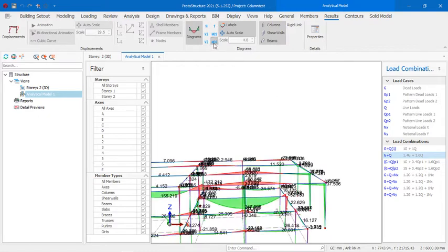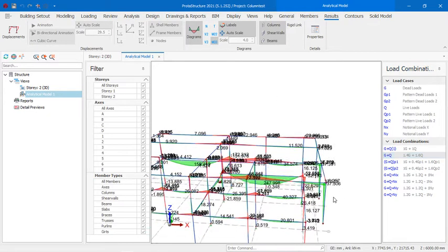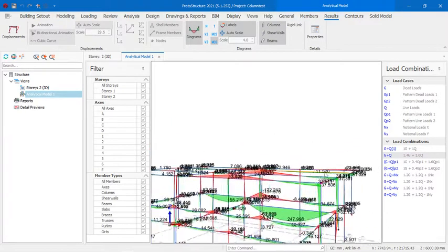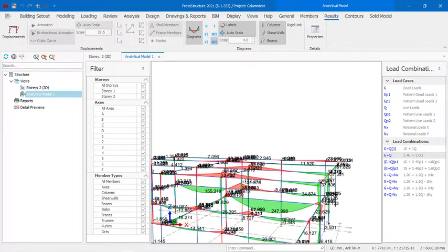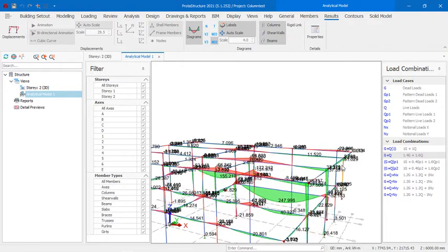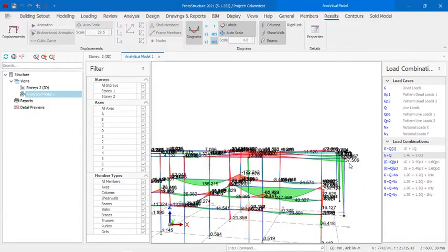Now in that case, what you have is very high moment in the upper part because it's dangling. So that will result in very high reinforcement in this beam, this beam, this adjoining beam, and it will also require higher reinforcement in the column.